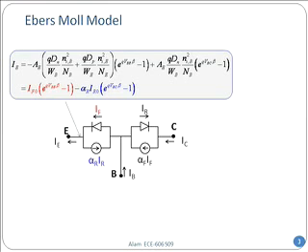We derived a formula for the emitter current, which had this diode component shown here in red, and also the current source component shown here in blue. Look at this: IF is by definition IF naught multiplied by the voltage dependent factor. The whole thing is called IF. And correspondingly, IR is the whole voltage dependent thing multiplied by IR naught.